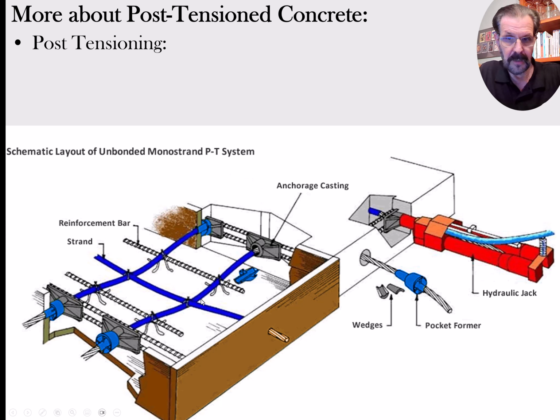With the post-tensioning that we do for a house slab or a slab on grade, many of the pre-stressing strands end up in the center of a 4-inch slab, and so then they're equally in the center.